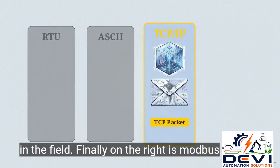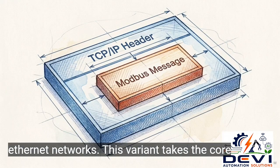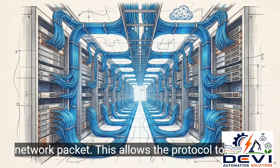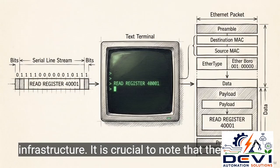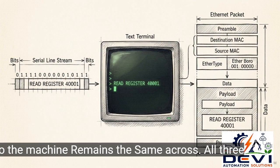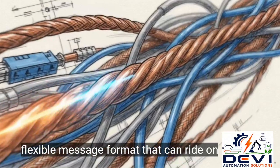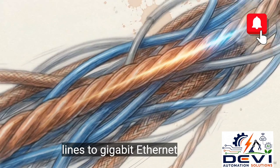Finally, on the right is Modbus TCP/IP, the variant engineered for Ethernet networks. This variant takes the core Modbus message, strips away the serial addressing, and wraps it inside a standard TCP/IP network packet. This allows the protocol to utilize high-speed, multi-node Ethernet infrastructure. It is crucial to note that the internal payload, the specific instruction being sent to the machine, remains the same across all 3 variants. Modbus is not tied to any specific physical wire. It is a flexible message format that can ride on anything from basic copper serial lines to gigabit Ethernet cables.